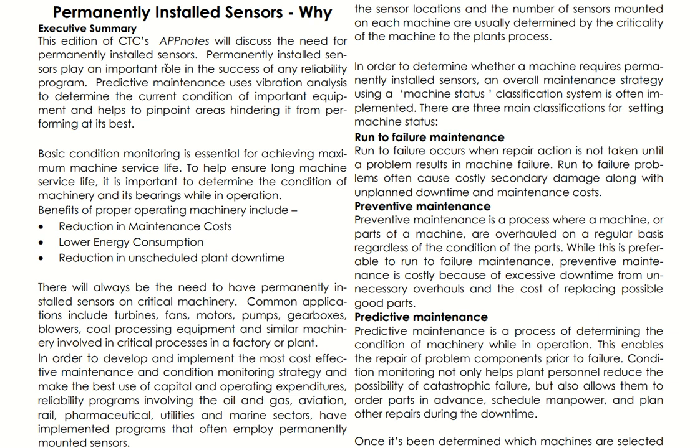The failure of a sensor will lead to changing the accessories of the instrument, plus changing the mounting as well. Sometimes only because of the sensor you have to dig a hole in the wall, or fabricate a new wall. So the selection of a sensor which is going to be mounted permanently is very important.